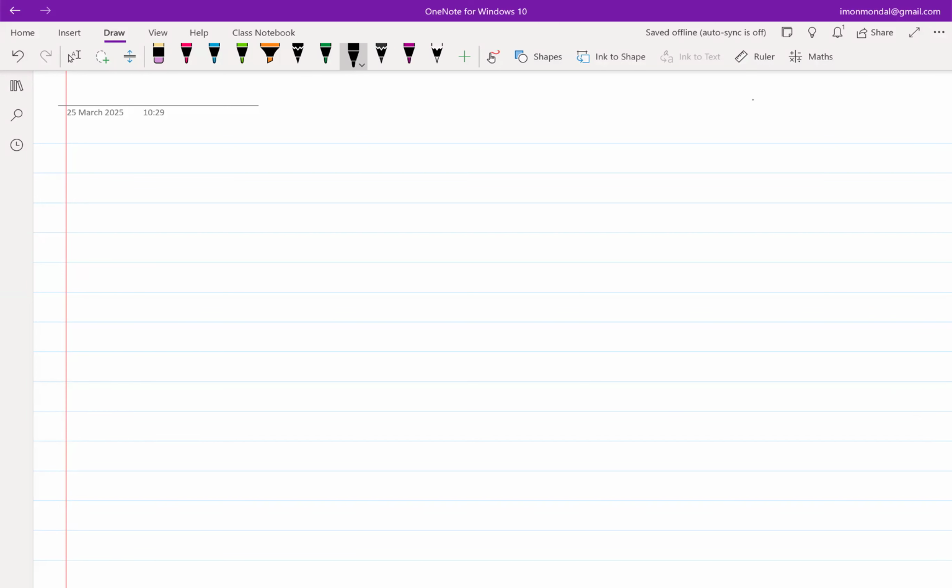Even in wideband systems, people use those metrics to characterize their circuits. It can be a receiver, an amplifier, or a filter, but still these IIP3 and P1dB numbers are often quoted. So even though strictly speaking they were introduced for RF, they have generic use.